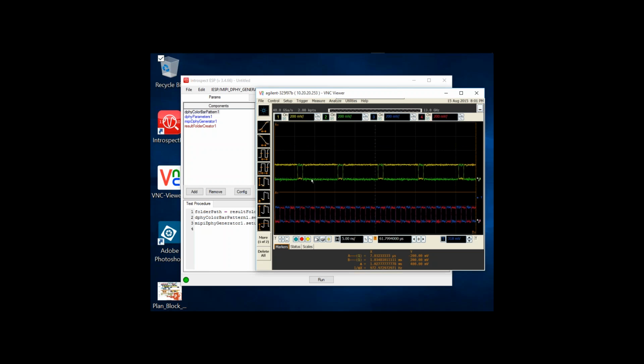And so what this section of the pattern does is really it's transmitting a 0 in a sea of 1s, and that's a good test for receiver stress testing, especially as we inject jitter and DJ onto the line, to make sure that the receiver is able to detect an isolated negative going pulse, as we show here.